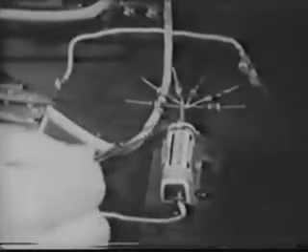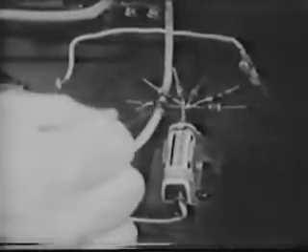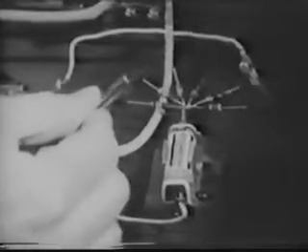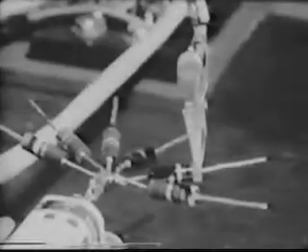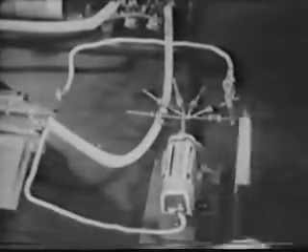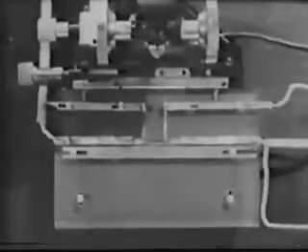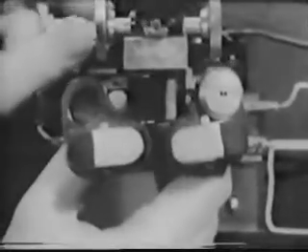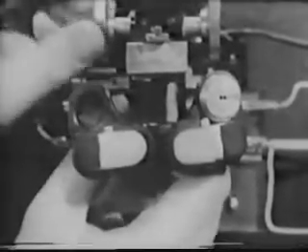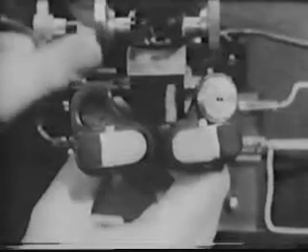The lead from the negative terminal is connected through a resistor to this brass strip, which holds the detector point. The resistor is chosen for best signal-to-noise ratio. This probe will be connected to the vertical input of the oscilloscope to monitor our detector current, and this is the ground. Now we're ready to focus the light on our bar using the right half of this binocular microscope for our lens system.